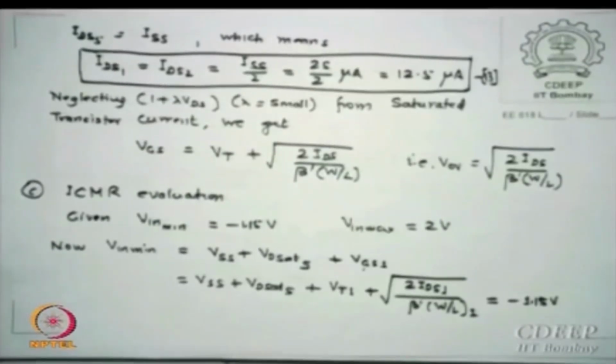So if you go below, VGS minus VT may not be smaller than or equal to VDS, then it will come out of saturation. So these are the values, and something going beyond is fair enough. If I increase VDS, fair enough, now how does it hurt me? Is that clear? So these values are essentially taken as min max, but actually they are max mins.